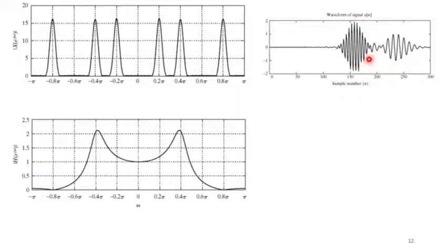So it will have gain equal to twice. Whatever the amplitude at the input was, now it will have twice of that. But the frequency component present at 0.8 pi will have output almost equal to 0. And you understand why? Because the response has a very small value for this frequency. So we say the highest frequency component is significantly attenuated.